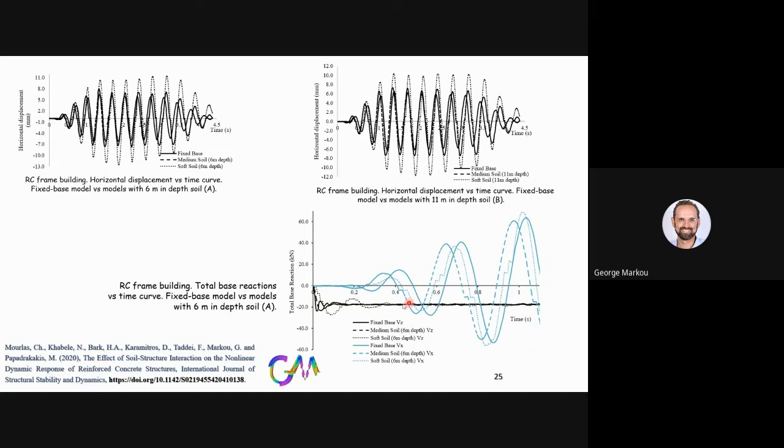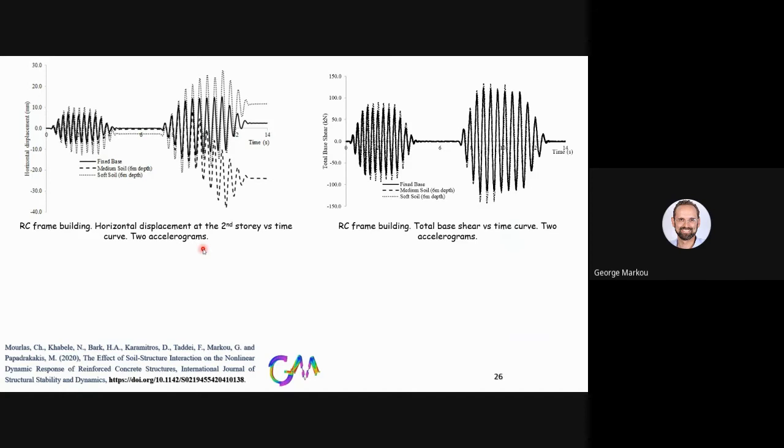So this is just the beginning of the analysis. We apply the loads and the dead load, the self-weight of the structure, then we have a settlement of the soil, and then this oscillates a bit and then it stabilizes. Now, the interesting part was the actual deformation and the dynamic response of the structure when the second accelerogram was implemented.